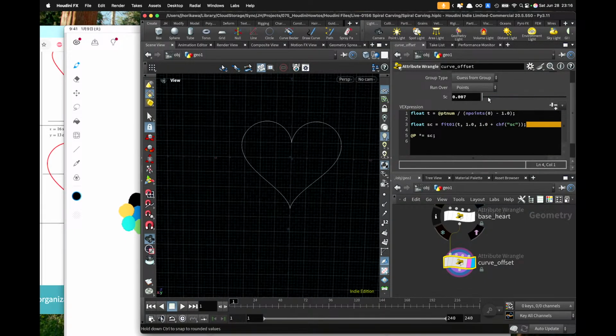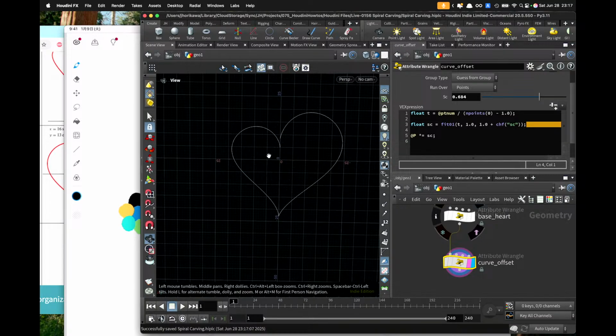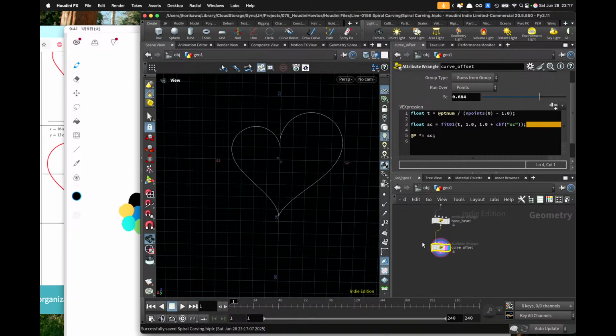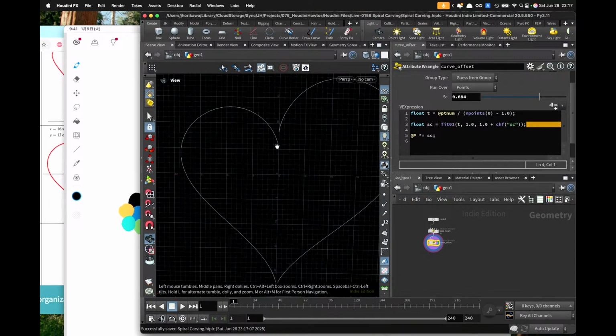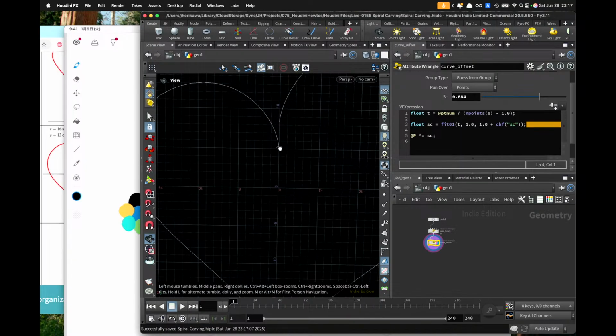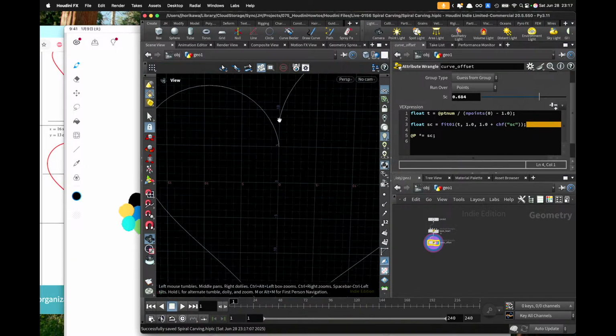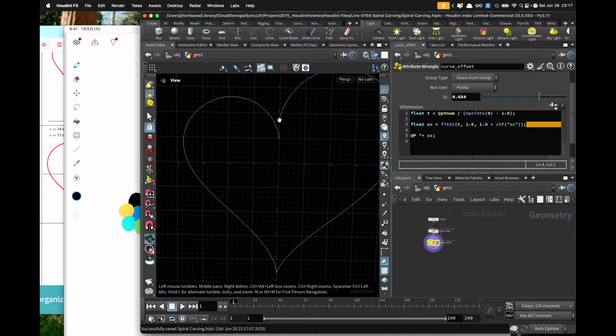Just like that. Okay, so that's good. So this is the base curve setup for 2D. Now what I want to do next is to continuously scale each pattern so that the previous curve is scaled so that the starting point will be touching the end point of the previous curve, and use that scaled curve as the next iteration and next curve for the next step in the loop.